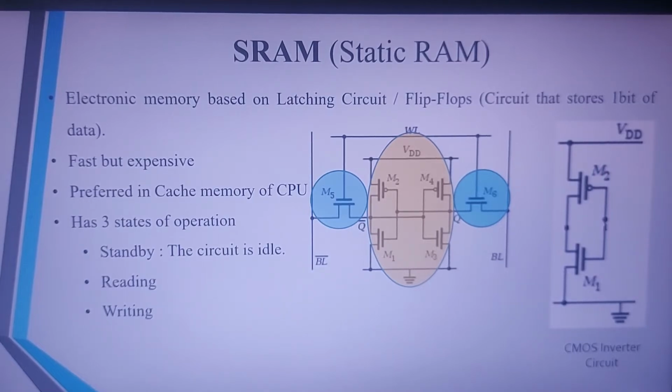And we know by basic electrical principle, when a wire goes very long, its capacitance also increases. That is referred to as parasitic capacitance. Now due to that capacitive effect, there is a delay in the data flow, so that causes additional time to read the cell. So by driving two lines, BL and BL dash, the circuit is optimized so that the data can be read comparatively faster.